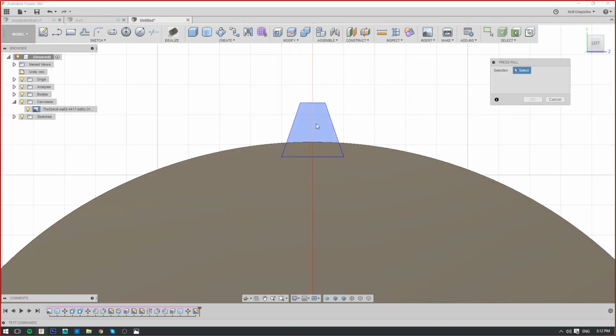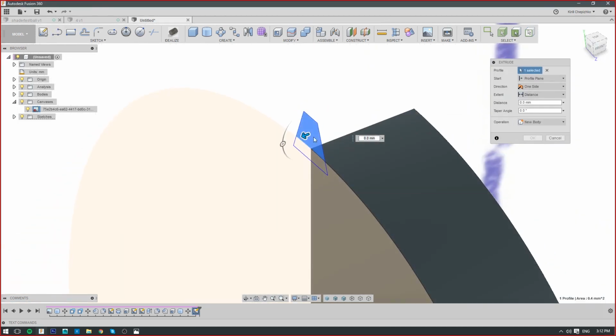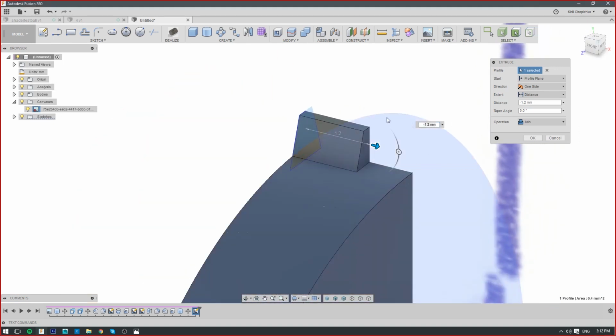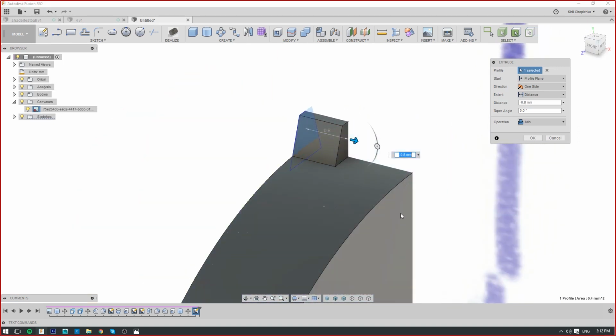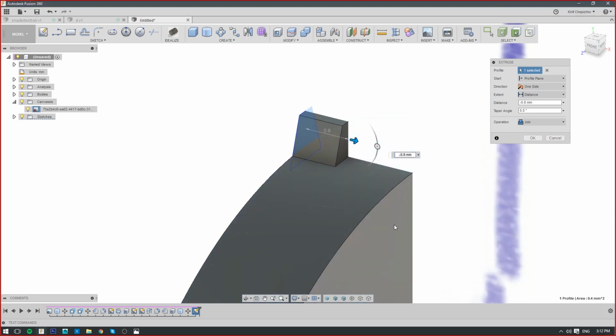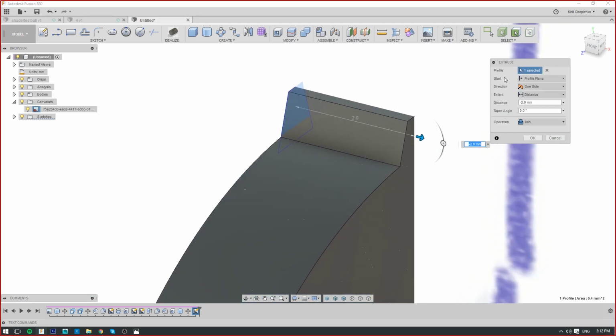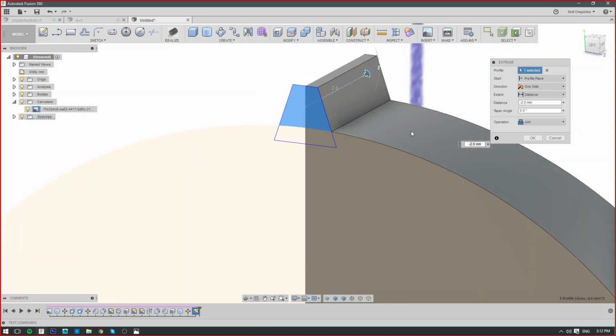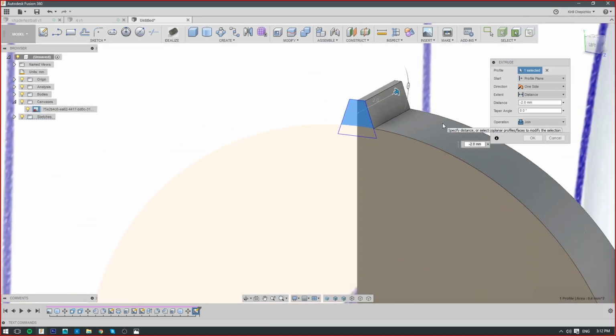So you just have one, you press pull it. Again, I don't remember if I mentioned, but when you press pull, if you want something to match exactly, you just click on the face that it needs to match with. So we have this, and again, two options from here.